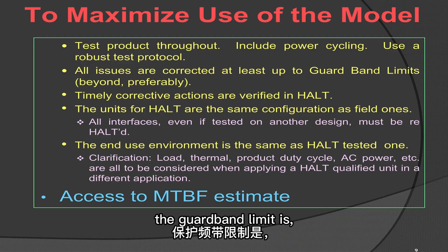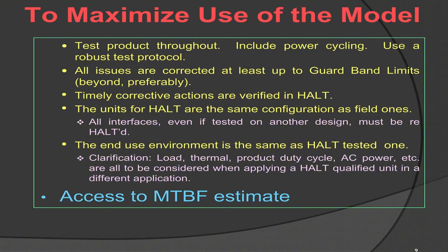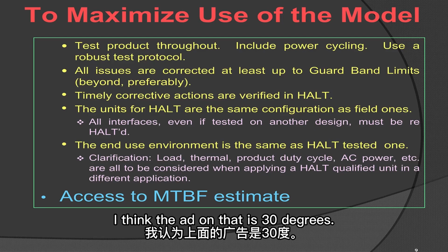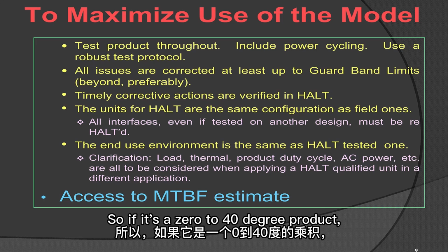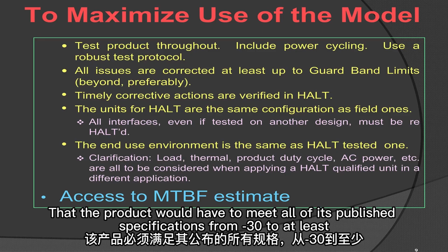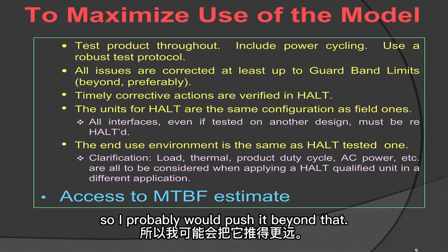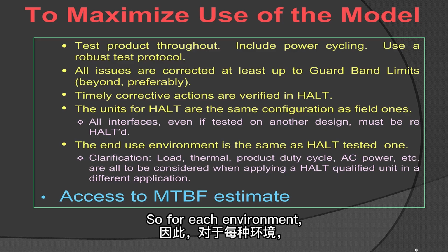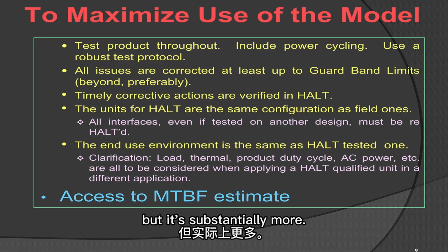Okay, the guard band limit is whatever the product specifications are. We add, for instance, in the commercial, I think the add on that is 30 degrees. I don't have my slides in front of me. So if it's a 0 to 40 degree product, then the product would have to meet all of its published specifications from -30 to at least 70. 70 is quite benign, so I probably would push it beyond that. So for each environment, for instance, if it's an outdoor environment, it's not a 30 degree adder, but it's substantially more.